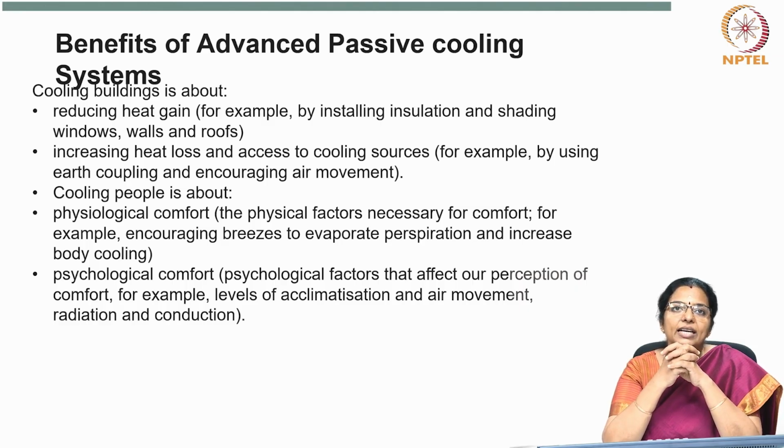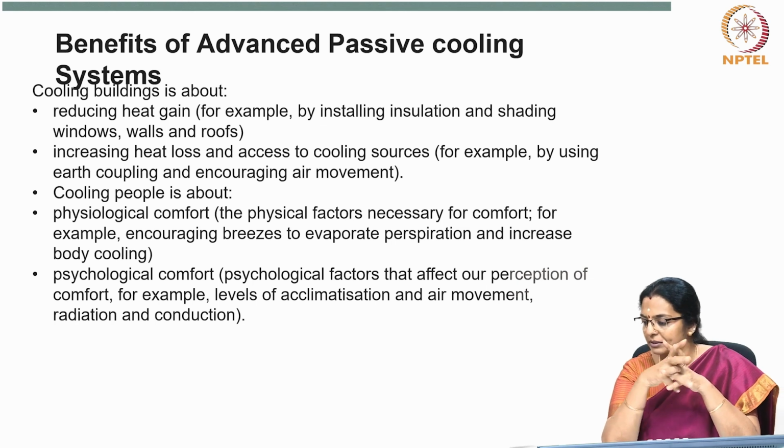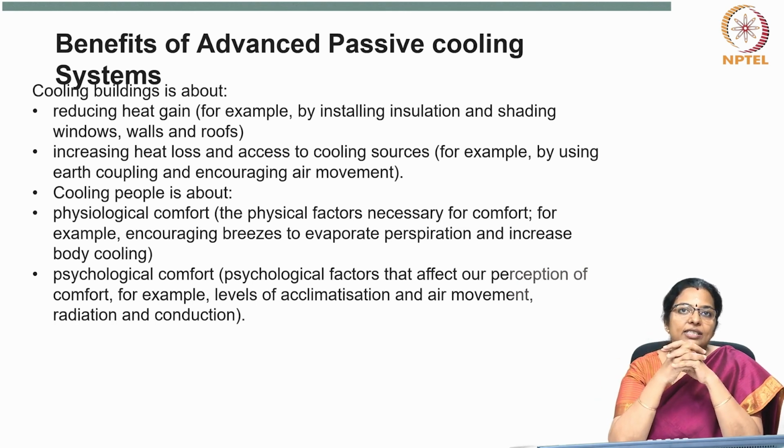So, cooling a building is about reducing the heat gain, for example, by installing insulation and shading windows, walls and roofs, and increasing heat loss and access to cooling sources, for example, by using earth coupling or encouraging air movement.